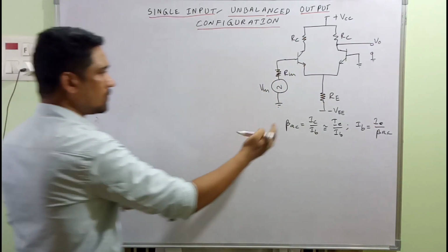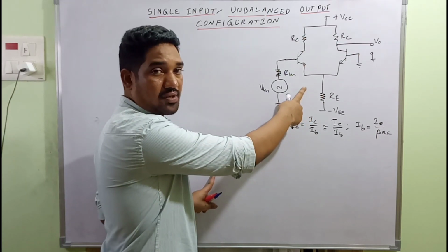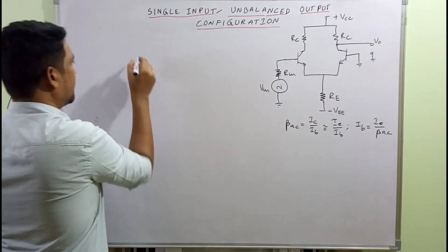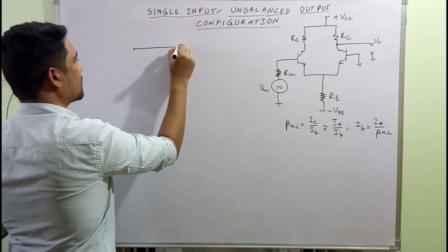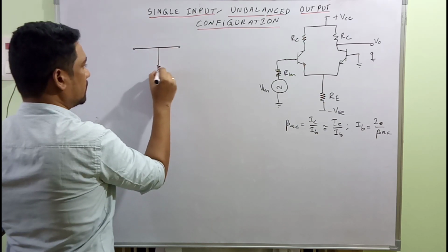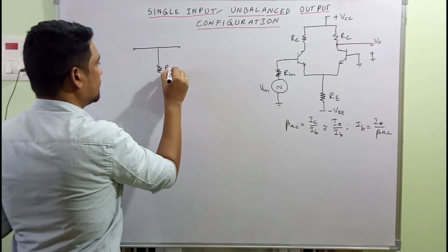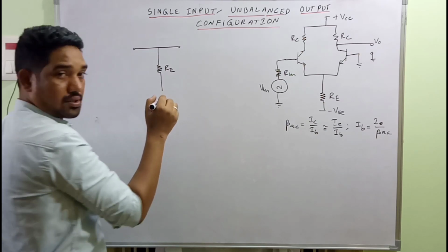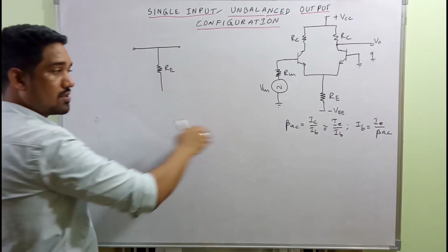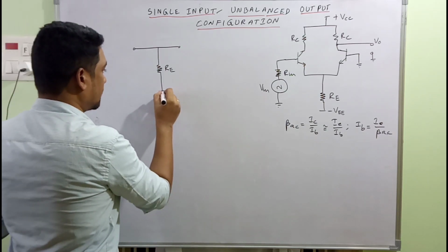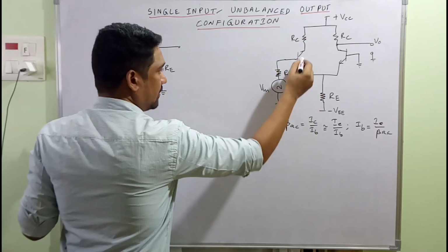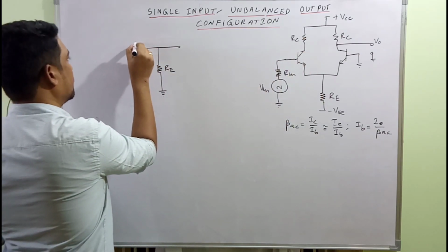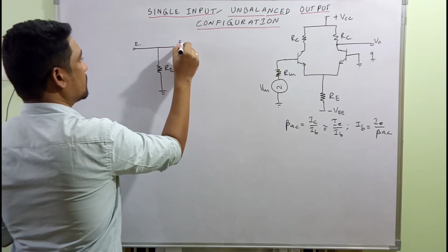So, reducing this circuit to its AC equivalent. What is that AC equivalent? Here two emitters are short circuited like this and commonly connected to an external resistance RE, and the other end of the resistance is connected to what? To minus VEE? No. In the AC equivalent, we neglect all the DC sources, so it should be grounded, right? Coming to this side, the transistor is short circuited, and this would exist like this. Let it be the emitter. I've told you it's emitter 1 and emitter 2.